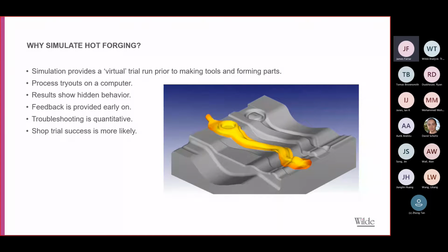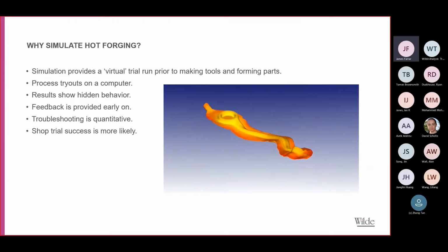So you can run these tryouts on the computer. You'll be able to look inside the part, see how the material is going to flow, and show hidden behavior that you might not see, such as flow defects, and get that early feedback to help you improve the design or narrow down your design. And that will hopefully lead you to have much more successful shop floor trials.